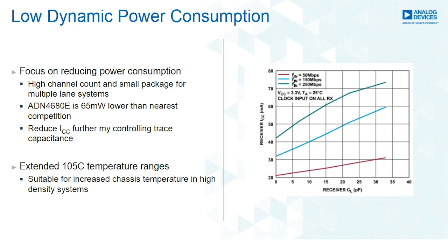The fact that each of the transceivers are half duplex means that each transceiver can be individually configured for either transmitting or receiving. So this lets the same device or even the same piece of hardware be used and play the role as either the controller or the peripheral device in a SPI network. So that's shown in the circuit here.